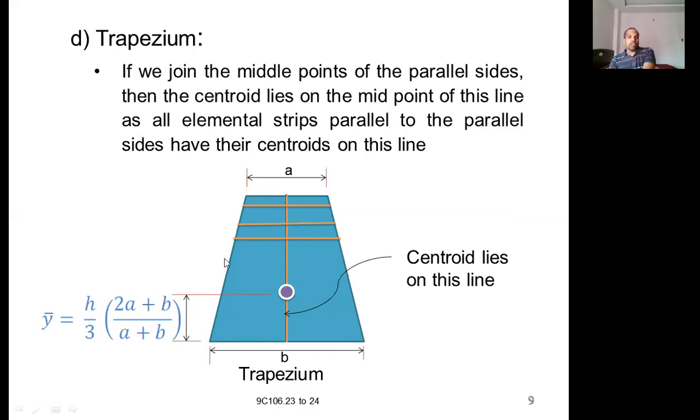Again, to find the centroid using first principles, this is not a regular figure, so it is a composite figure and you have to divide it into one rectangle and two triangles. Divide it, number them 1, 2, 3, calculate the areas and the moments of areas, and find the centroid of this figure. In this case we need only the y bar, because the x bar lies at the center, on this line. There is no need to calculate the x bar for this case.